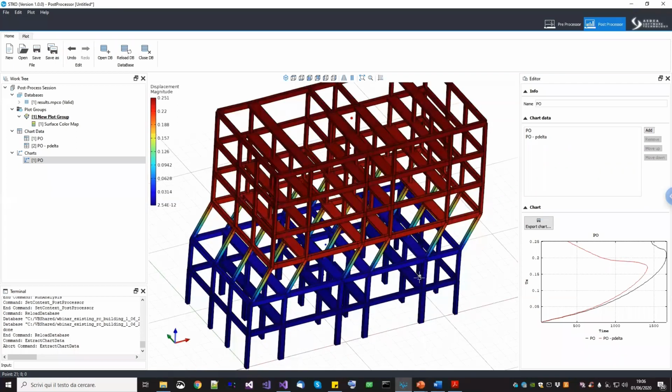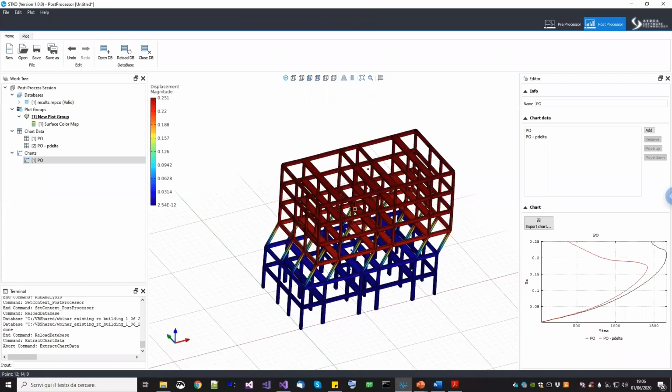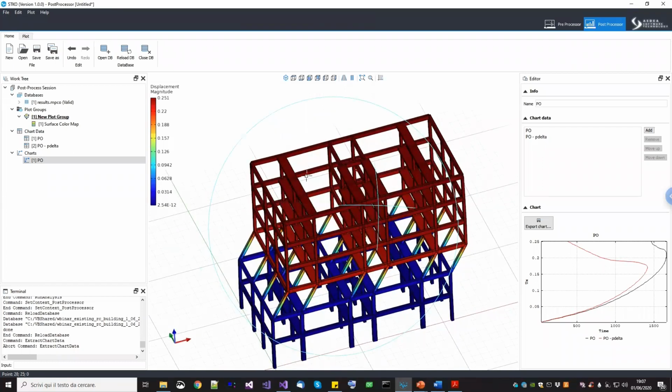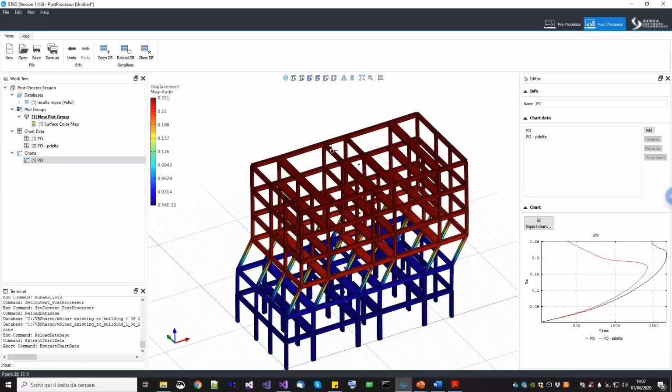So we started with just material nonlinearity, then we added kinematic nonlinearity. Now I want to show you something that happens very often when you have fiber cross sections with the rigid diaphragm. Probably you have seen it already on the OpenSees website. It is a pretty known effect. You know that in beams you do not expect to see high normal forces, okay? So you expect the normal force to be 0 or approximately 0. Now in this case it is not like that.